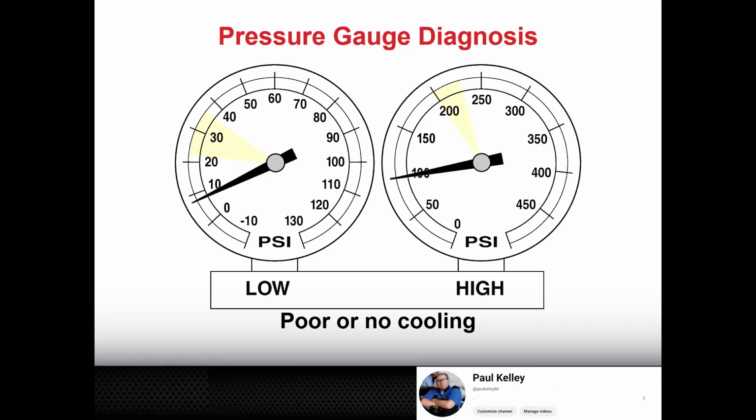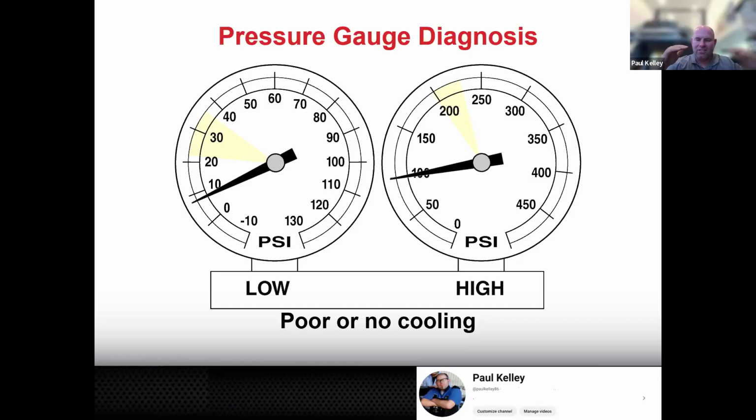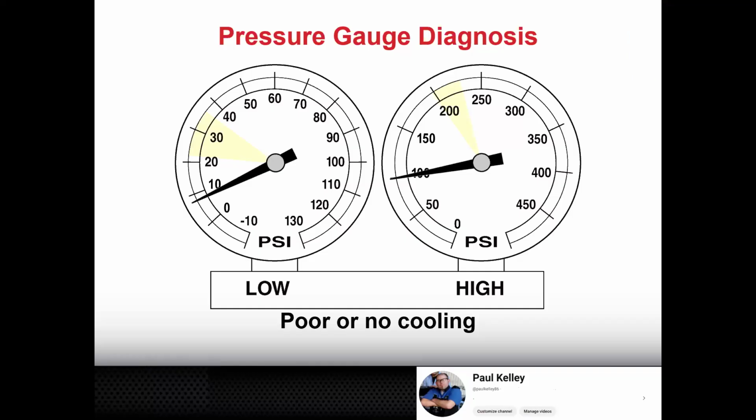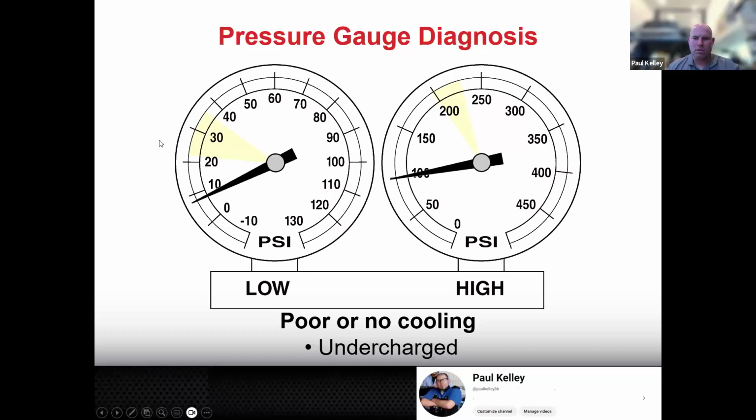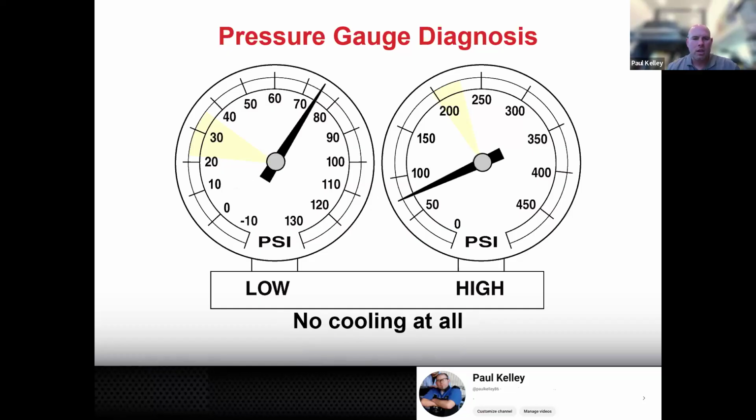The compressor's not lazy. Like if the compressor's lazy, they're both kind of similar, right? Both of these are low, and one person did get it. I would say it's low refrigerant as well. Bada bing, bada boom, which we call undercharged, low refrigerant. Yeah, exactly. Nice. All right, another one.